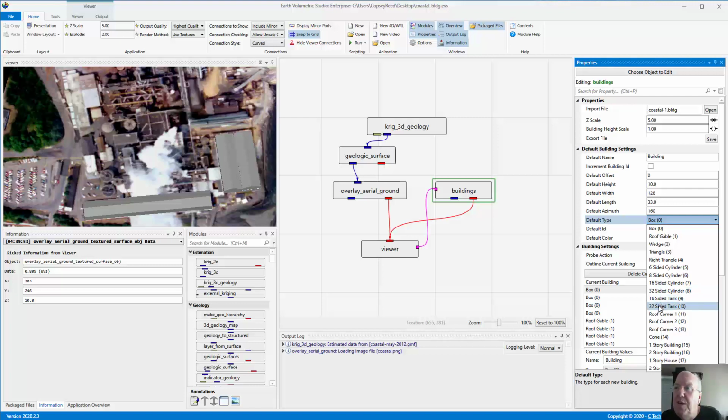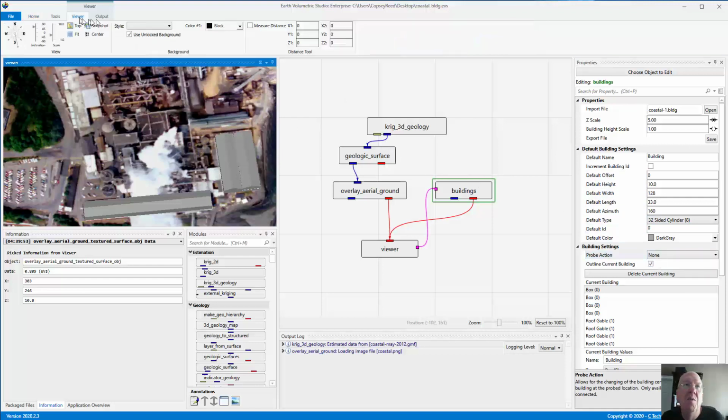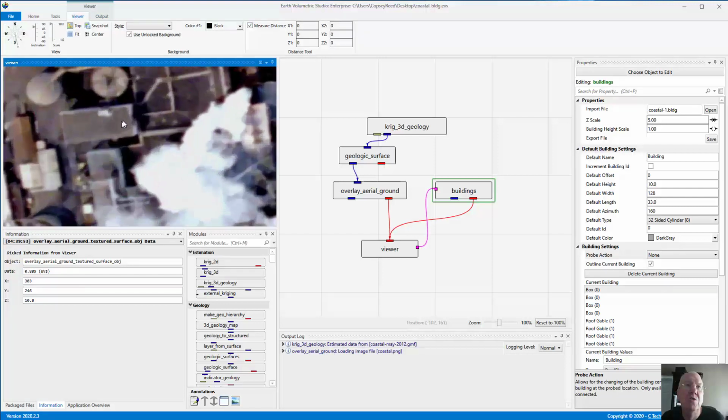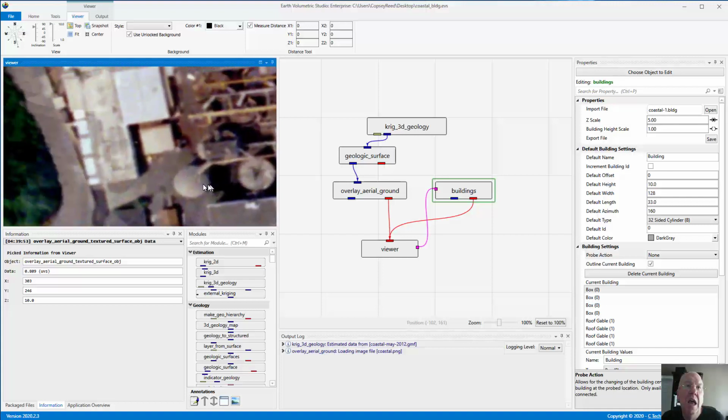Now, these other 2 down here are horizontal tanks, like underground storage tanks. This is what we want in this case. So all I need to do is figure out the size, and let's again go back, switch this to none, go back to the viewer, and sometimes you're on the output, you need to click on the main viewer tab, and let's measure distance, zoom in on a tank. I'm going to do this one here first, and let's just measure across to try to get the diameter.